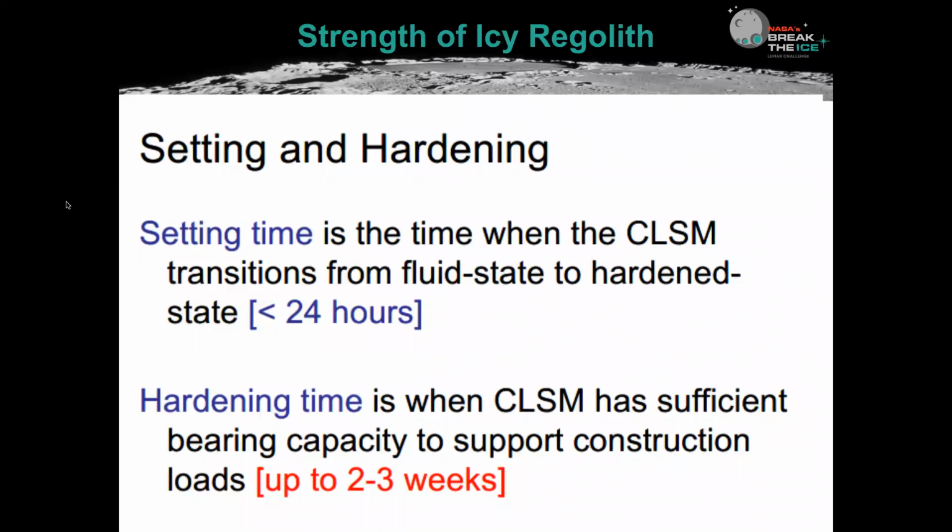One of the important characteristics of this material is the setting time. Initial set for it to go from a fluid state to a hardened state is about 24 hours or less. But if you're really looking to put some load on it at some point, then we probably have to wait at least 2 to 3 weeks, because it does take a longer time to set because of the amount of water it has in it. Next slide.